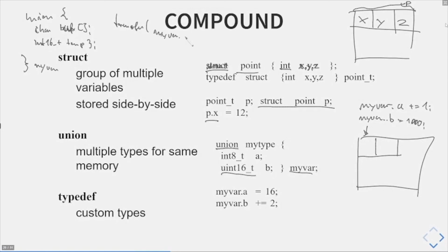So I have as an argument this myvar.buff, so this memory block, but interpreted as a buffer of single bytes that should be written to from the sensor, which are transferred then. Then later on in my program, once this has been transferred, I can refer to this as the actual temperature and interpret this as a 16-bit integer.